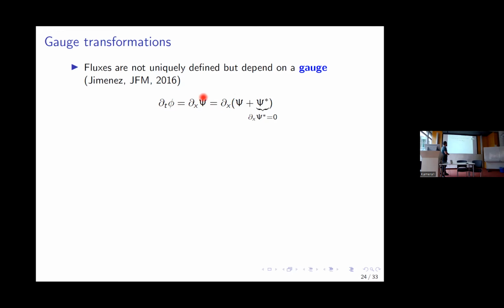the idea is simple. You take the fluxes that I have in the equation, and I can add to those fluxes any flux with zero divergence, and the new fluxes I have generated will produce the same effect on the flow as the original fluxes. I cannot distinguish between the two of them. They are physically equally relevant. This is a problem that has been known for a long time in electromagnetism, but I think it has not been applied to fluid mechanics.